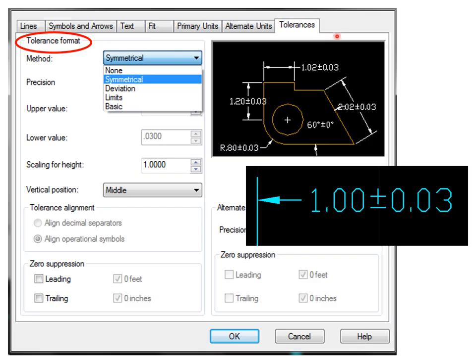I'm only going to briefly mention tolerances in this chapter because we will spend 2 chapters on just talking about tolerances. Just don't forget that tolerance, for now, is how much the part can be off by. So when you ask a machinist, hey, I want the thickness of this metal plate to be 1.00 in thickness, the machine shop is going to ask, well, how much can we be off by? You have to give them wiggle room. So this is referred to as a tolerance.